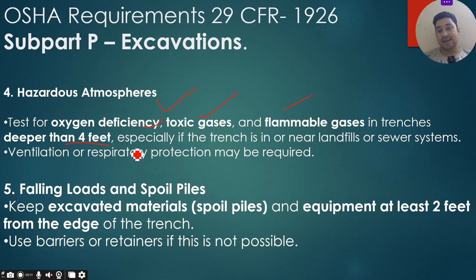Especially if the trench is near landfills or sewer systems, you have to conduct these tests. You know that sewer systems generate toxic gases. Okay, so that's why you have to do it. Ventilation or respiratory protection may be required, as per the depth of the trenches.